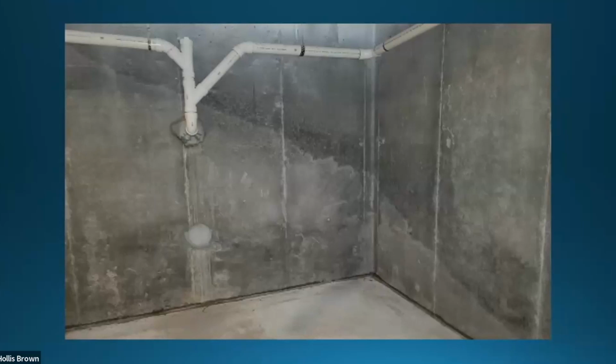And there are some bad things that'll happen if you vibrate too much. One is your gravel will start to settle, so you'll have more paste and sand up top and more gravel down below. Or you can actually blow the form out, which happened to one of our guys, a kid that we had working for us. He was afraid to tell anyone that he had the vibrator stuck, and so he just kept vibrating in the same spot and it blew the form out.